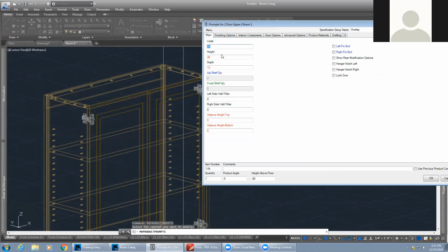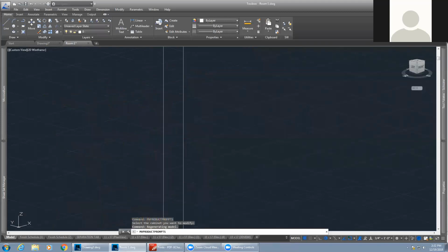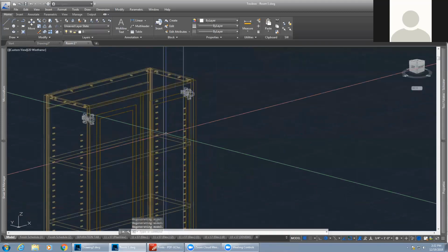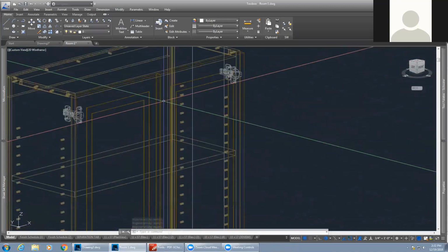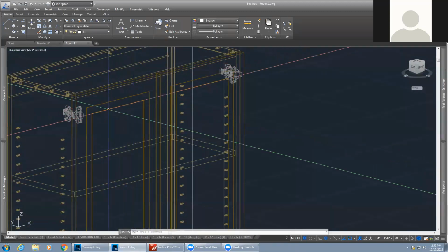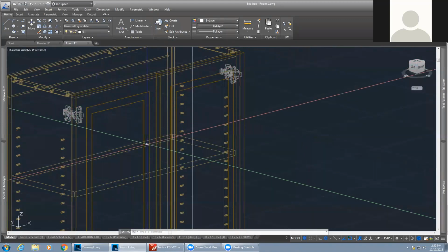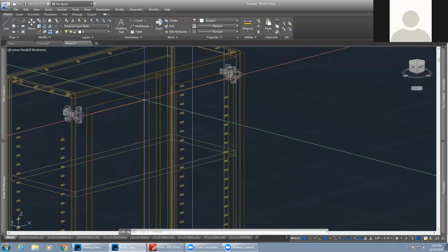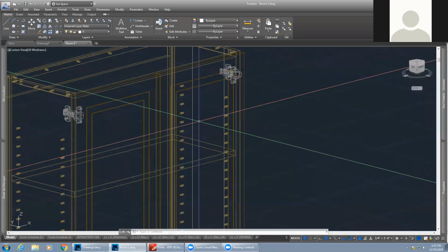intent there, when we change this to a different width and or a different height, all of the door information changes as well. So now we have two completely different doors, but all the metal band information, not only does it remain graphically equidistant from the edge of the door, this is actually generating G-code for the CNC machine. So when it cuts this door out, it's going to put that groove in the correct spot on every single door. So you can imagine the amount of time savings that has.